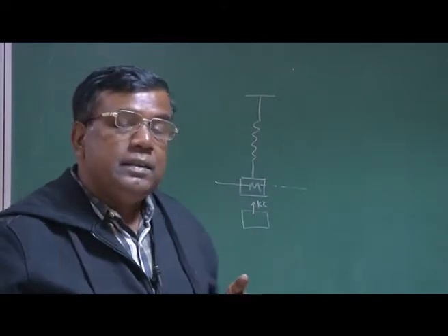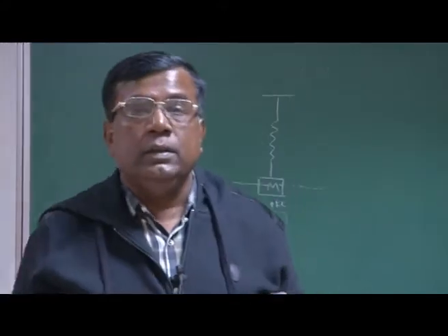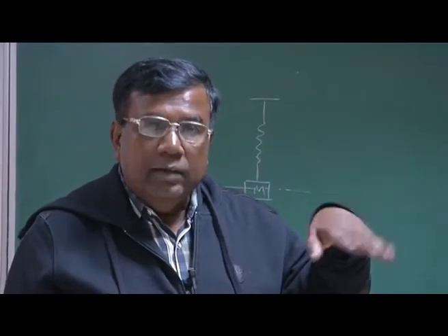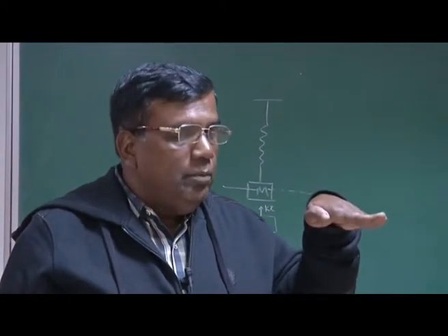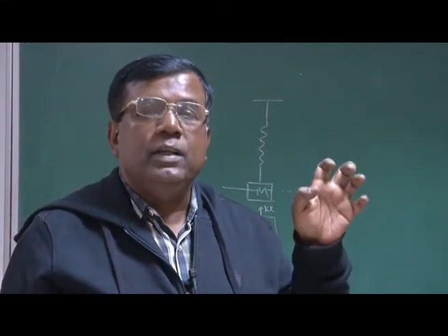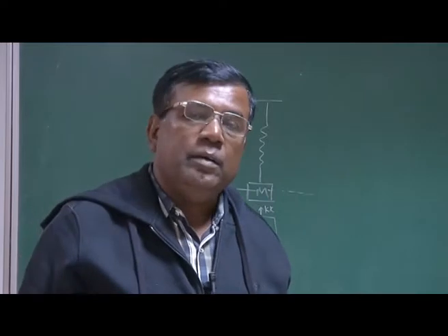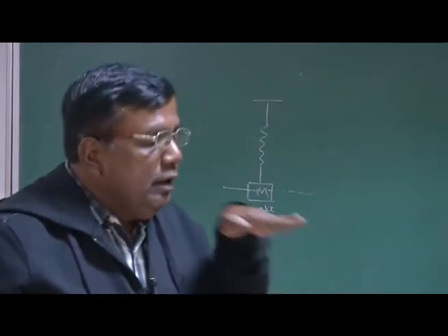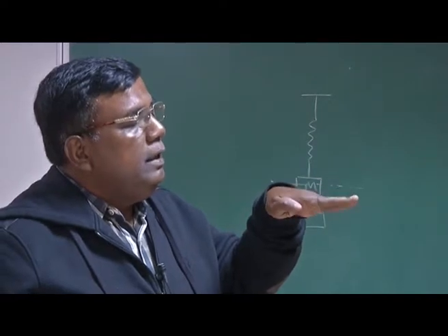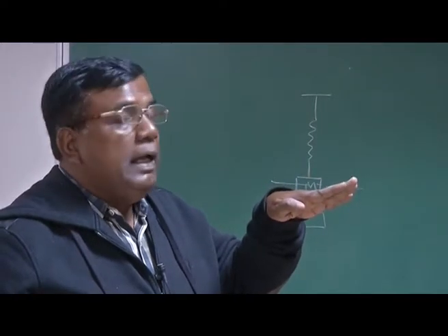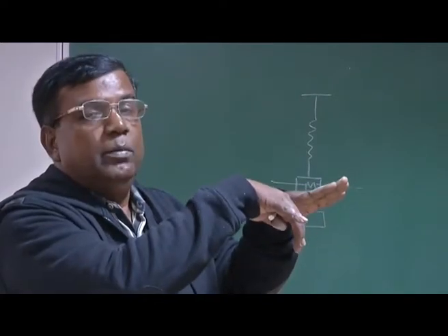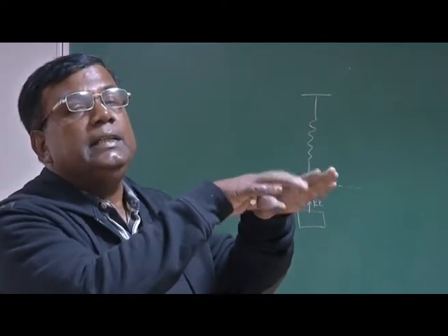For a mass spring system, the spring does all this work. But for an aircraft, what is the agency that will ensure that the moment I deviate from the equilibrium, there will be a restoring moment which will try to take it back to the equilibrium? If it is disturbed and its attitude has increased, then the aircraft should have a mechanism which gives a nose down moment to ensure that it has static stability.